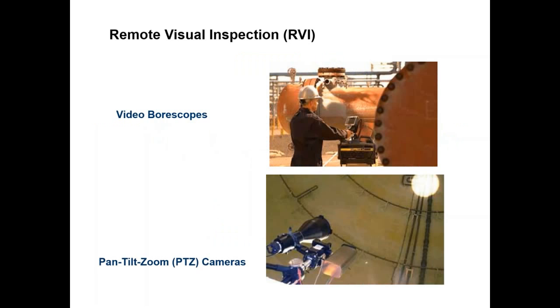Now, what I will do is give you an overview of what some inspection methods are used to evaluate the extent of corrosion or even do forensic analysis even in the field. Easiest way is, of course, to record the corrosion activity as a function of time, or using borescopes or cameras that allow you to access areas that are very hard to access, or even an online monitoring system that transmits the images remotely.